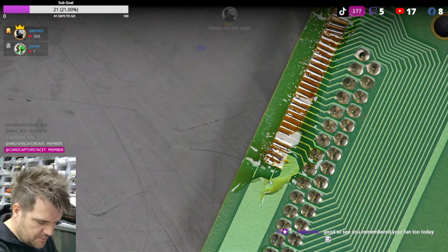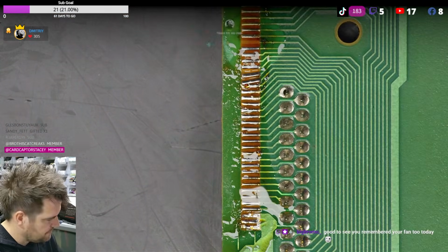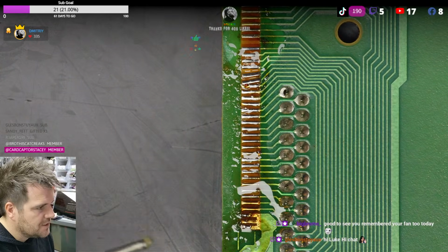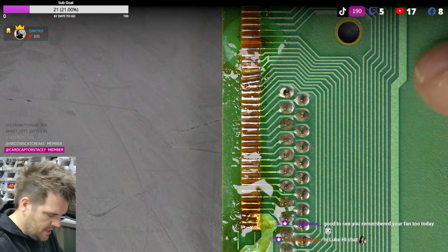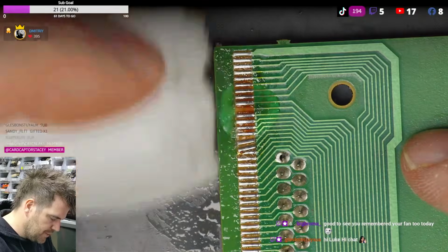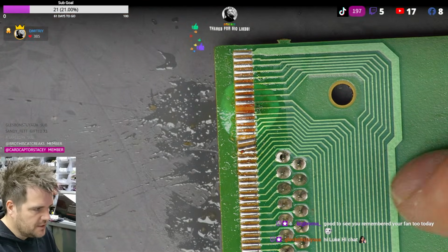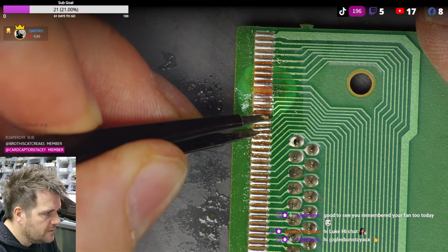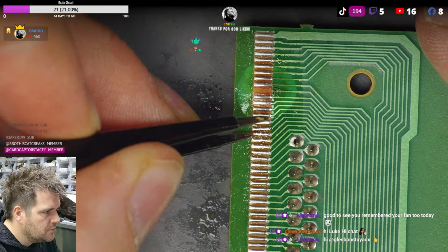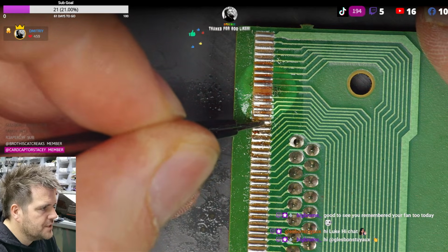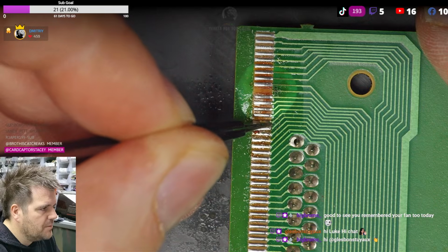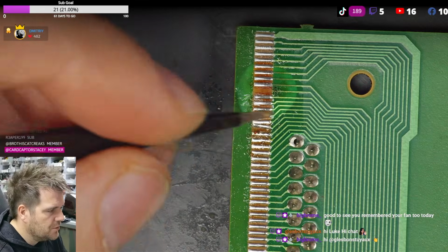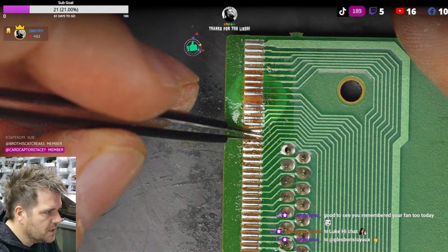So putting a connector on here is probably the best thing we can do for it, because the connector is going to anchor up and stay nice and solid, and these pins then won't be under stress either. So you can see these two pins are moving. You can reposition them while they're in, but we want to probably make a note that once the LCD connector's on, we might want to check these are going to the right place, or maybe even bond wire these two things over to there. We'll see what we do, but let's take note of them.